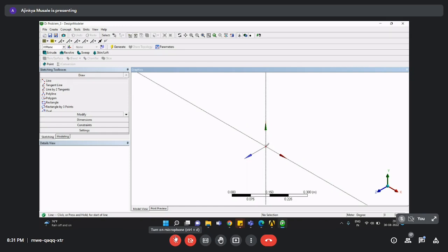I want to start my line from that point. When P appears, I will simply click, and H means horizontal line. If I drag it vertically, it will give me V. You can turn them off also. Constraints are there; you can go into that setting and turn them off if you don't need these suggestions. But now I need it, so I kept it as the default.